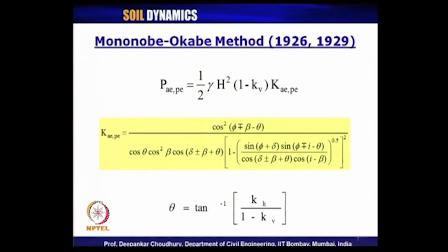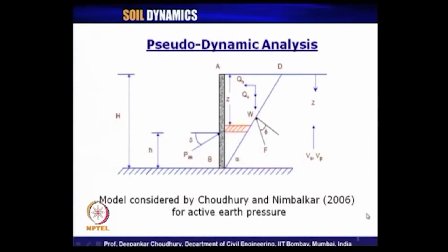If you remember, we talked about it during the module when we discussed liquefaction of soil, to take care of the stability of the soil. This is the criteria we have to satisfy. So, from that criteria this theta comes, and for stability phi should be greater than this theta, that is, the soil friction angle should be greater than this theta.